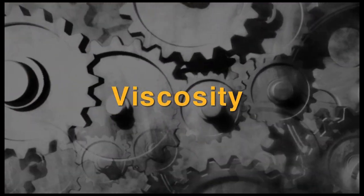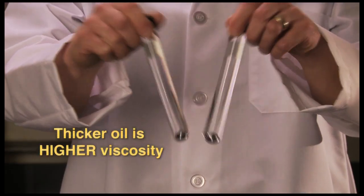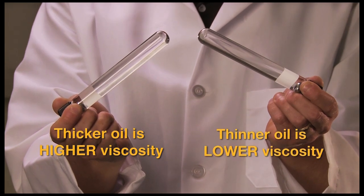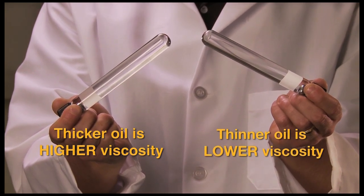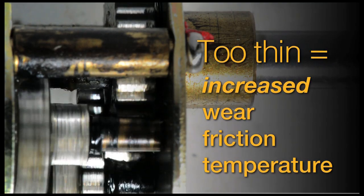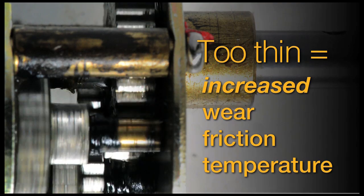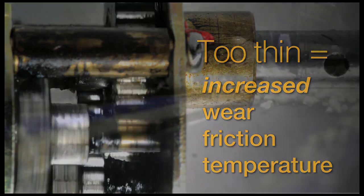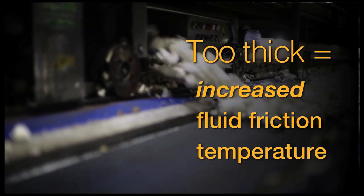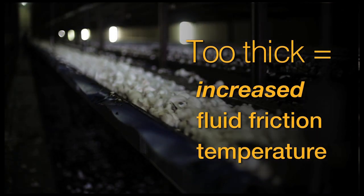Viscosity is the most important characteristic of any lubricant. Basically, thicker oil is higher in viscosity, and thinner oil is lower in viscosity. If an oil is too thin, it will squeeze out, resulting in increased metal-to-metal contact, increasing wear, friction, and temperature. But if an oil is too thick, it will increase internal fluid friction and temperature, reducing the useful life of both the fluid and equipment.